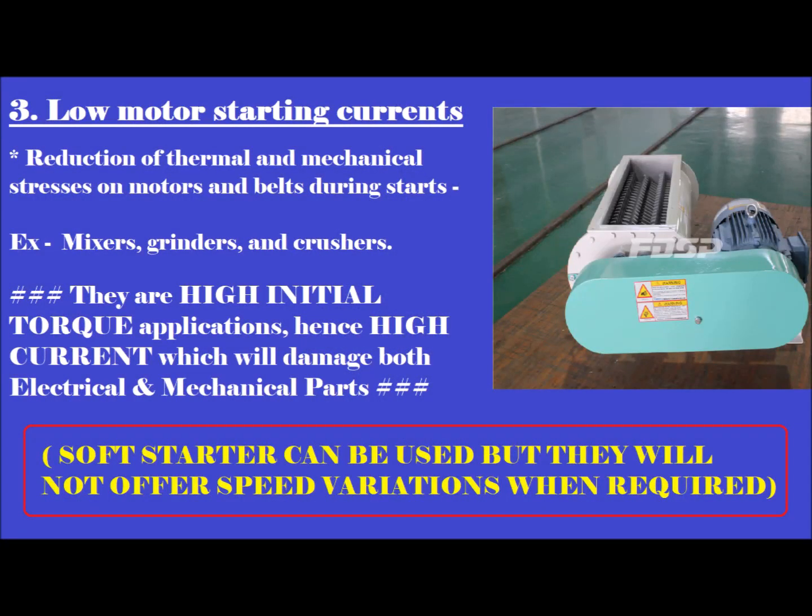So we'll come to the third point, that is low motor starting currents. To understand this point properly, you should go to a drive and see how much current it is taking initially. It will always start at 0 and reach a certain set value of current over a period of time. The advantage of this is that it helps in reduction of thermal and mechanical stress both on the motor and on mechanical parts such as belts or gears etc.